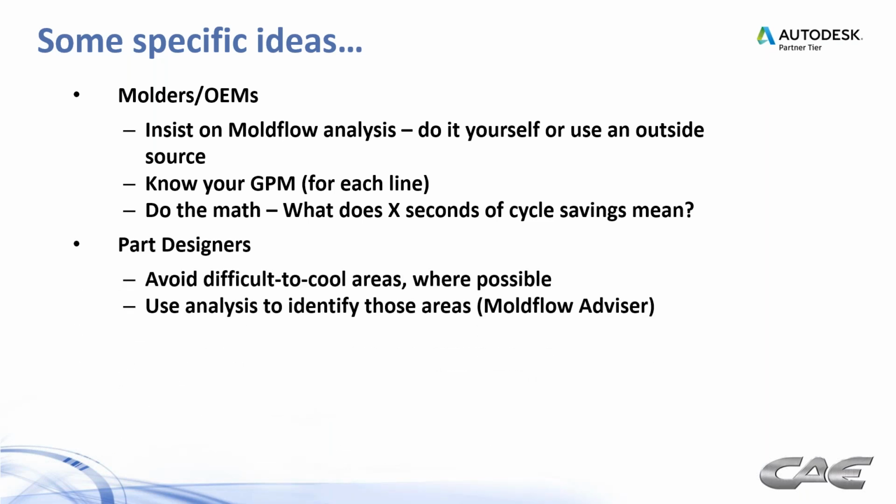For part designers, when you're designing your parts, avoid difficult to cool areas where you possibly can. Much of the problems that result on the manufacturing side for injection molding result from the part design itself. Follow those plastic part design 101 recommendations, and this is one of them for cooling. Try to avoid difficult to cool areas wherever you can. And then, of course, use analysis to identify those areas.